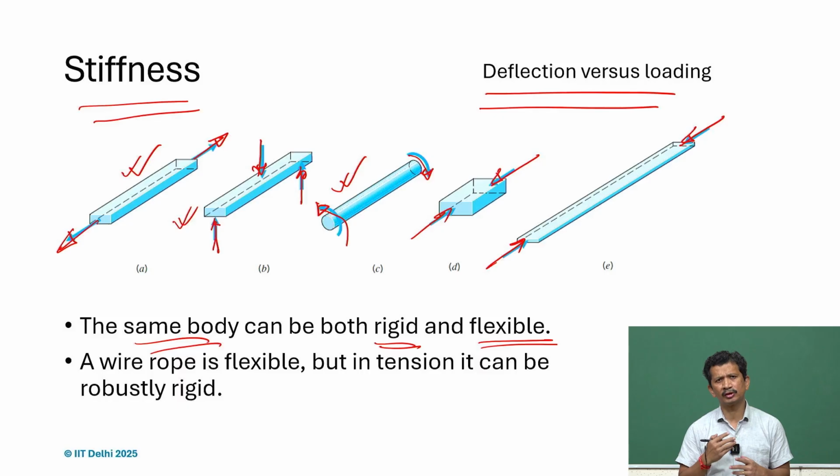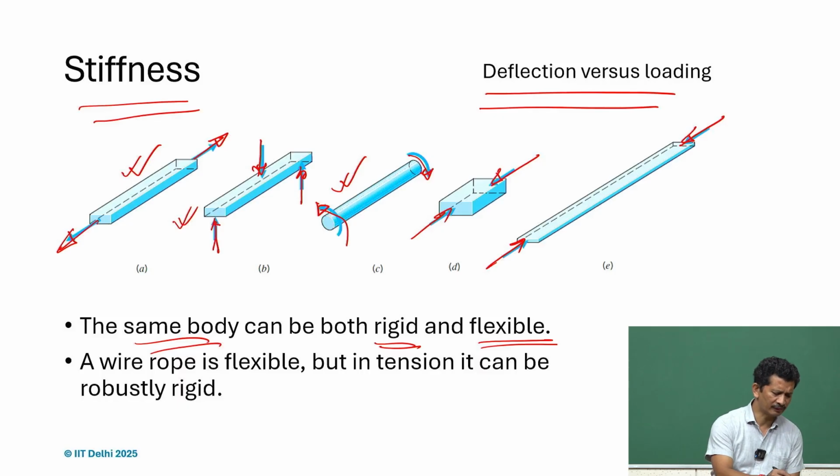So, we always talk in terms of degrees of freedom, or those directions: 3 translational directions and 3 rotational directions, and what the stiffness is in different directions. And in many cases, these individual members, these components, because of the geometry, can be rigid and flexible at the same time. So, for instance, in this case itself, consider 1 and 2.